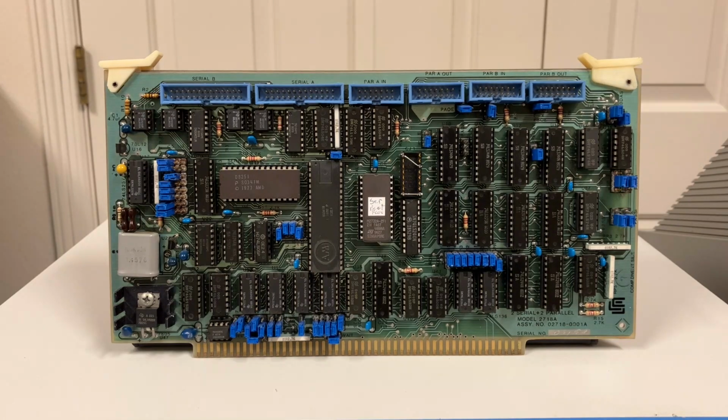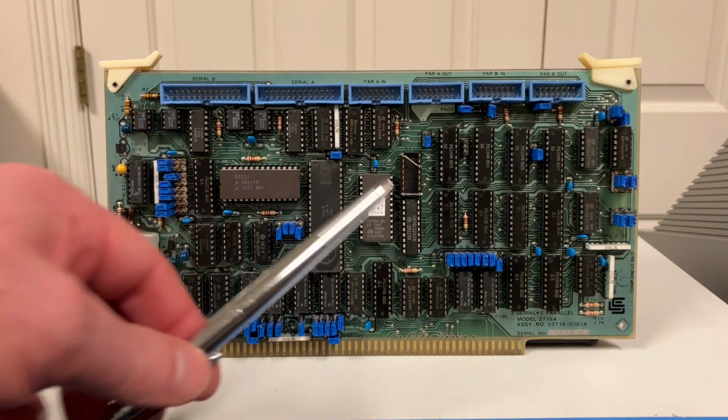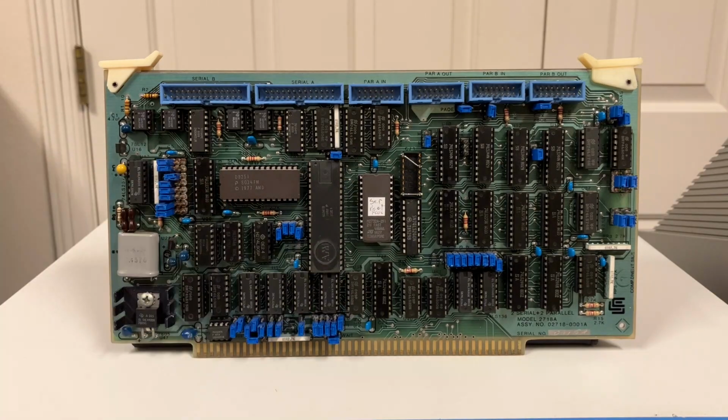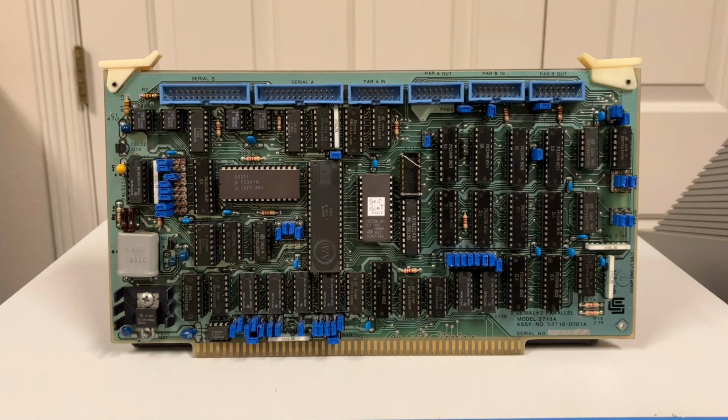And like the solid-state music board, we do that by choosing the right buffer that buffers this status register onto the bus. With a non-inverting buffer, like an LS244, we get positive true logic. With an inverting buffer, I put in an LS240, we get inverted data or negative logic like we need. So at that point, all those conditions are satisfied. We need to look just like the original SIO board as far as software is concerned.